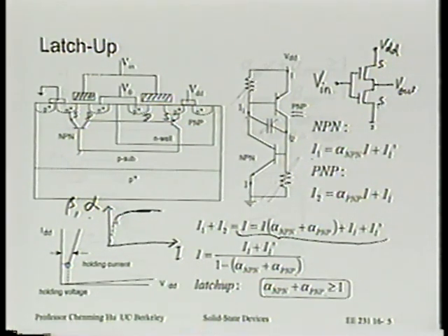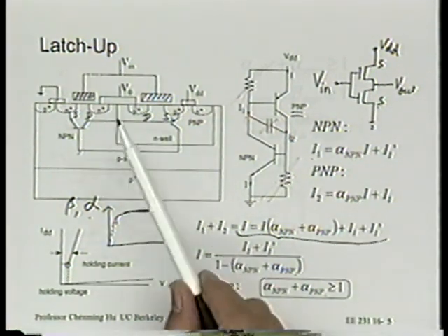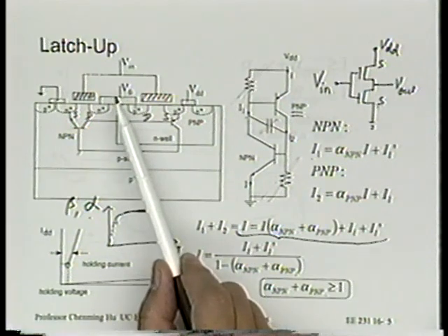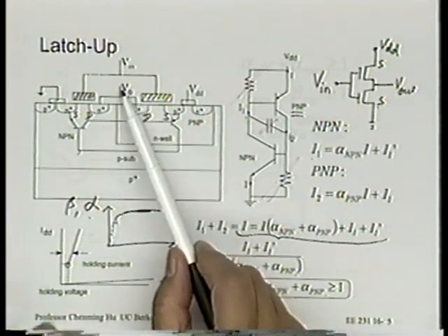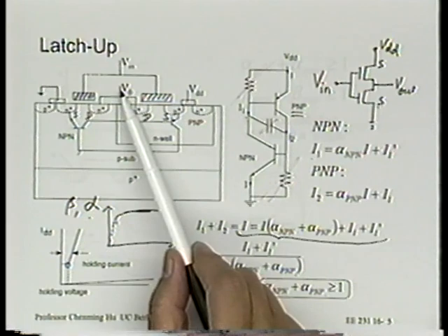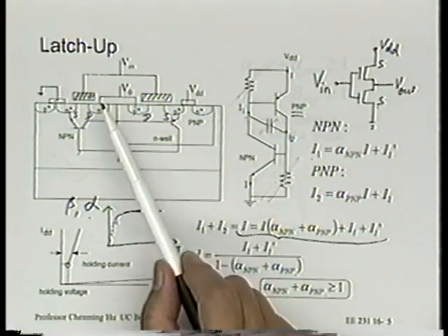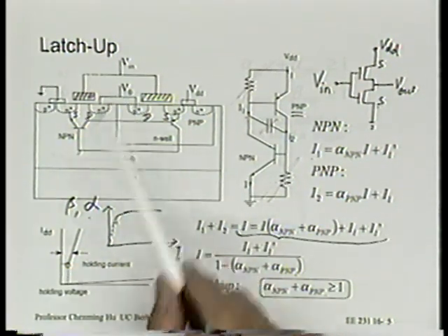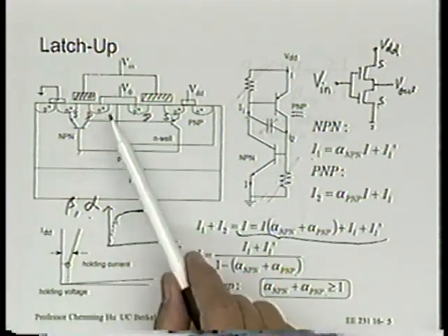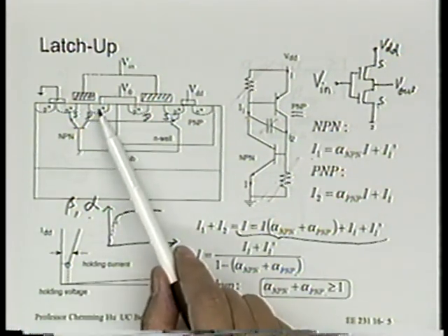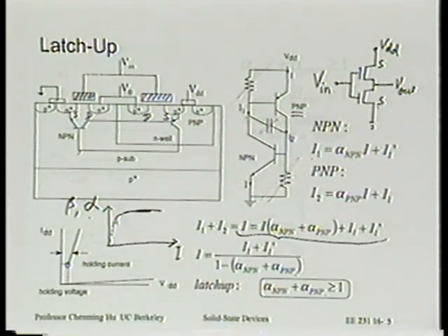Sometimes you will even see circuit boards designed in such a way that, for example, the power supply is connected before the output voltage is connected, because the output goes to leads that you have no control of. You don't know what voltages are on these output leads, right? They can actually forward bias your PN junction, for example. That will certainly give you a transient current, is that right? A transient forward bias because of inductive noise, let's say.